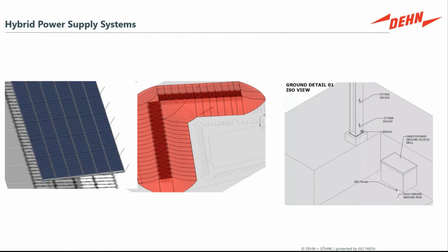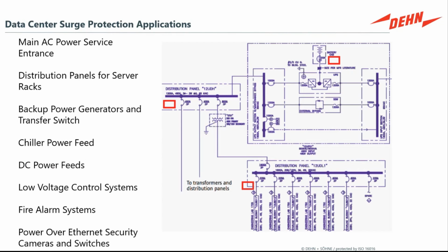And this is a nice illustration of what some of those legacy buildings look like that have now had parking garages, parking structures added with solar collection panels on them. And so these types of applications were never intended for a data center, a real finely controlled system. And now we're having to upgrade things like the grounding and bonding to make sure that they meet the lightning protection system that's required for a data center.